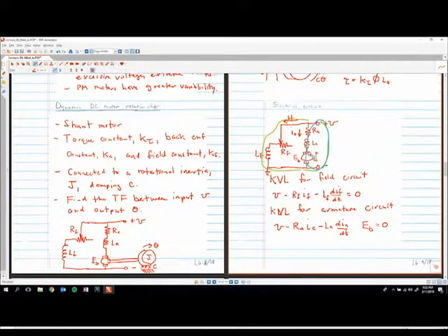So if we look at how the voltage changed going across this back EMF element, we've actually had a decrease in voltage, because the high side is, with a positive spin of the motor, this one, and this is ground. So the sign of this is actually going to be negative here, because we've had a drop in voltage across it. Any questions? That does trip up a lot of people in terms of that positive or negative.